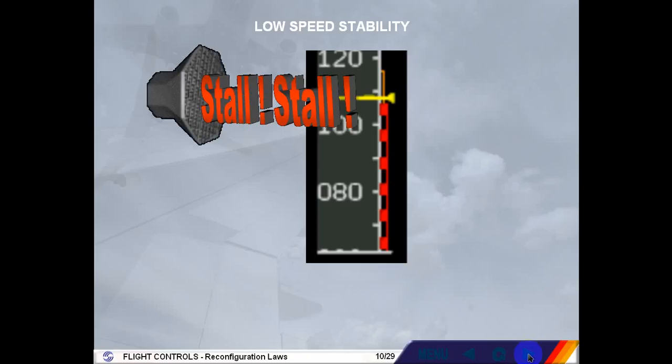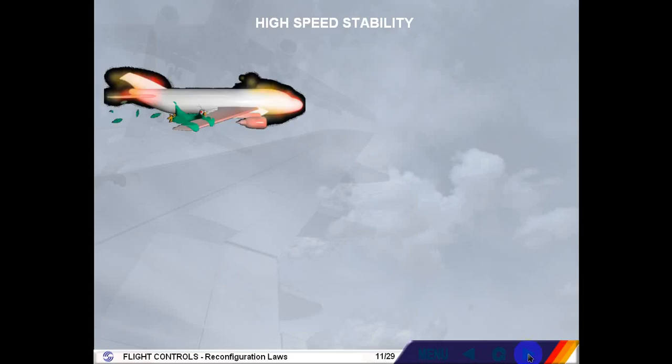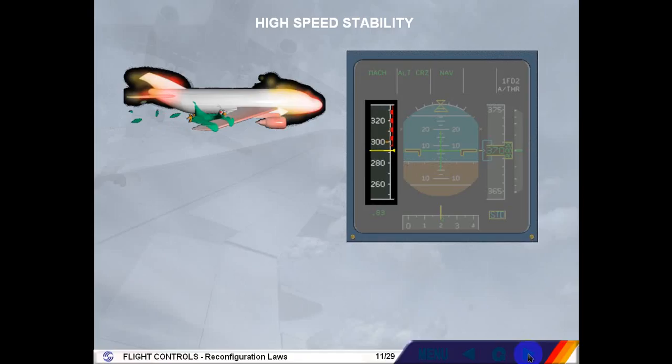Alpha floor protection is inoperative in alternate law. In alternate law, high-speed stability replaces high-speed protection. The green dashes are replaced by amber dashes on the speed scale. Above VMO or MMO, a nose-up input is introduced to raise the nose and prevent further speed increase.